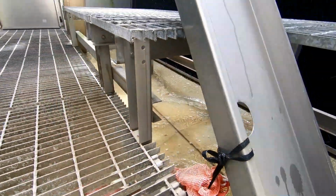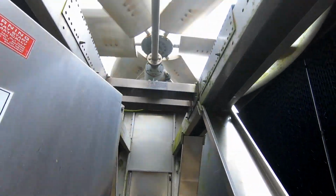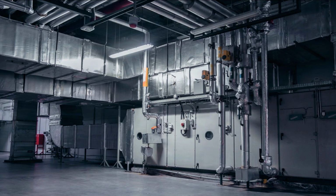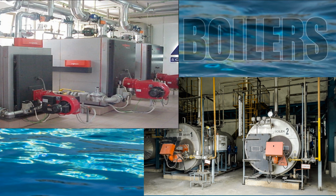The water is then moved to some form of a heat exchanger where it then removes heat from another system. In many cases, there will be a secondary loop that will flow through the building piping and pass through the coils in an air handling unit where the initial heat exchange takes place and the cooler air is distributed throughout the building. The water in the pipes then returns to the heat exchanger and the process begins again. There are other system components that can help with the heat transfer such as condensers, heat exchangers, and chillers, but we will discuss these in greater detail in other videos.